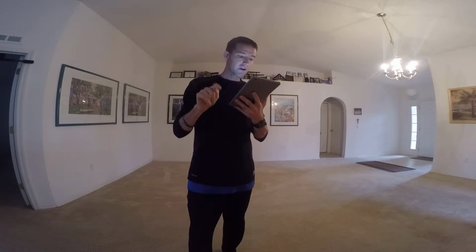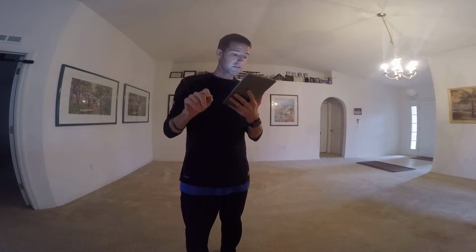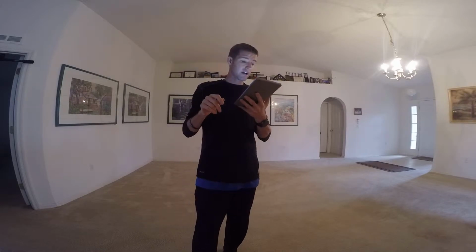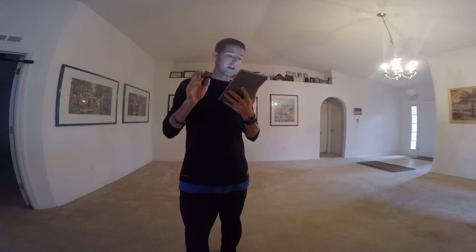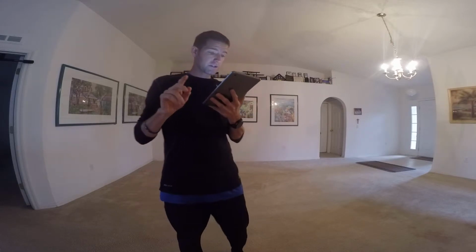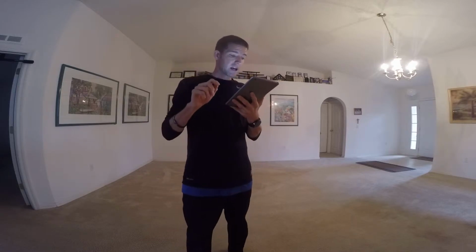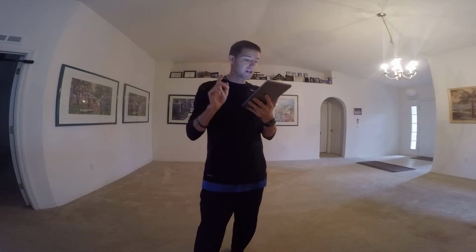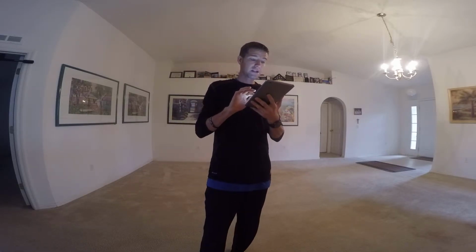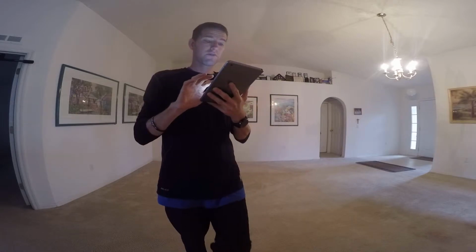In straight and level unaccelerated forward flight, straight and level flight is flight with a constant heading and at a constant altitude. Lift equals weight and thrust equals drag. If lift exceeds weight, the helicopter accelerates vertically until the forces are in balance. If thrust is less than drag, the helicopter slows down until the forces are in balance. As the helicopter moves forward, it begins to lose altitude because lift is lost as thrust is diverted forward.